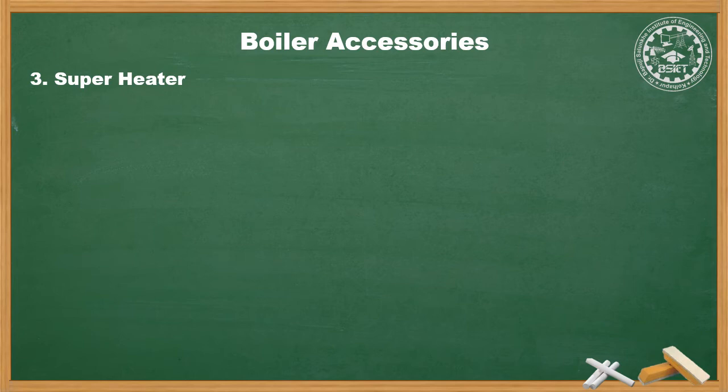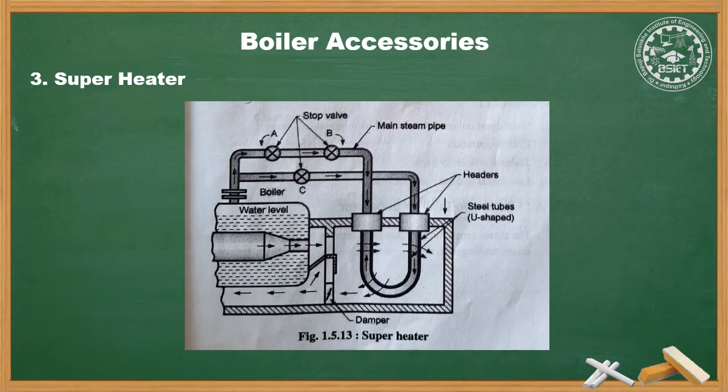Usually, where superheated steam is needed, a superheater is provided. The superheater, as shown in the figure below, is located in the path of the flue gases so that the heat of the flue gases is utilized. There are convective type and radiant type superheaters. It is connected with the economizer, so the flue gas flowing through helps to heat the water as well as the steam flowing in the pipes.